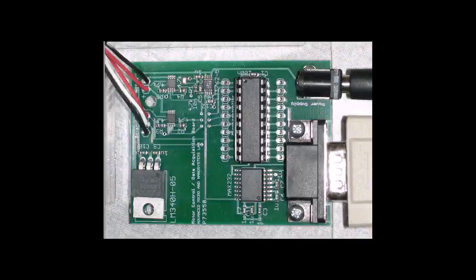Before I show the development of the real-time Windows target interface, I will first discuss how our system communicates with the host computer. Our system communicates through a USB to RS-232 conversion cable. The peripherals driver creates a virtual COM port on the host PC, which allows MATLAB and Simulink to easily read and write for high-level access to the mechatronic system.